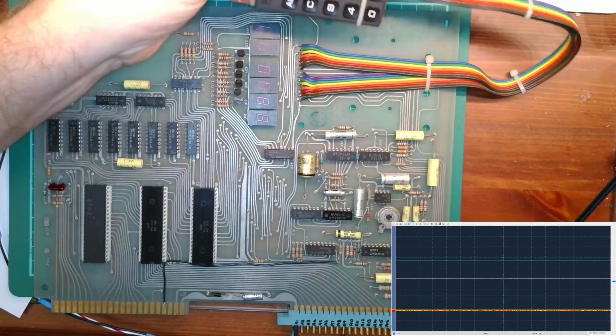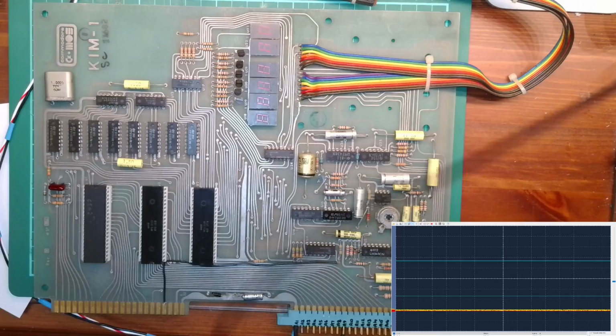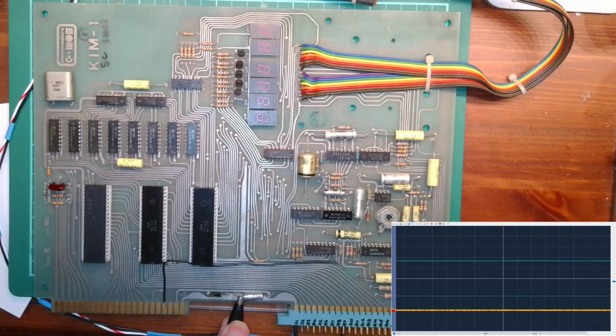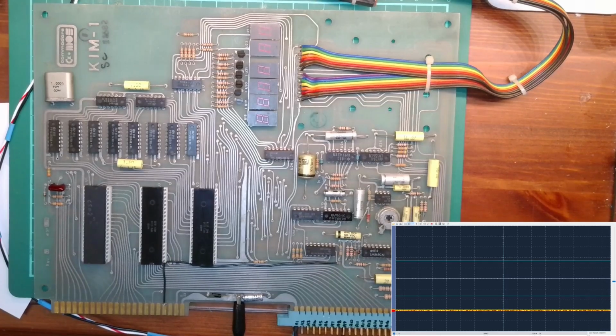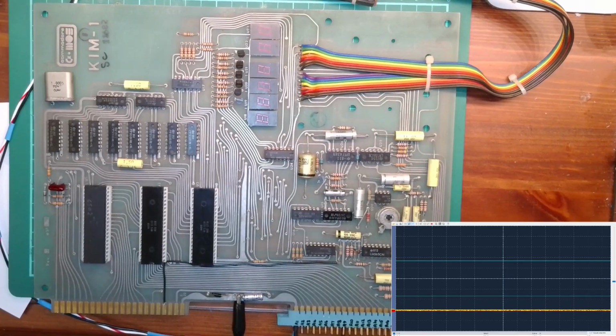So we put it back onto run and let's stick the scope on it. What I shall do is put the channel 2 screen onto that nice convenient 0 volts there. Then I'll use the channel 1 probe, because the 0 volts are joined together on the two probes. Now on the 6502 we've got a pin that pulses every time an instruction is operated. And let's see what pin that is. That's called SYNC. It's on pin 7.